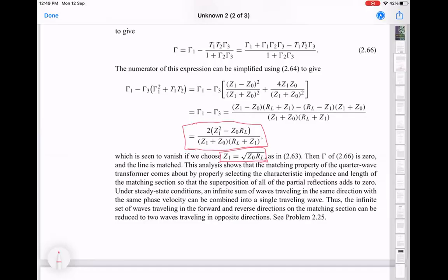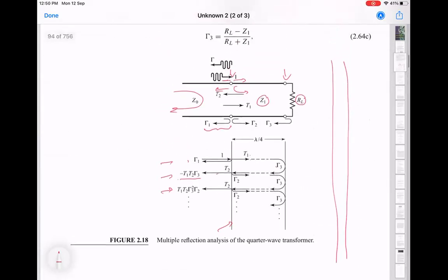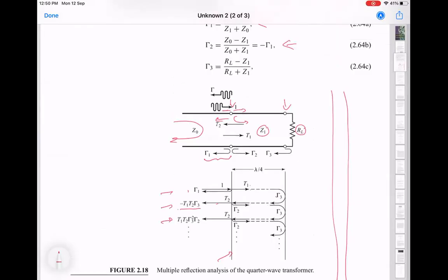So this is just to set up the equivalence that a time domain picture involving multiple reflections, or a frequency domain picture, which is the impedance description, will give you ultimately the same answer. But this will all work out only in steady state, like we talked about in the first lecture. But there is other things going on. So what basically it means is that if I actually send a pulse here on this line, so something finite, then the reflection coefficient,